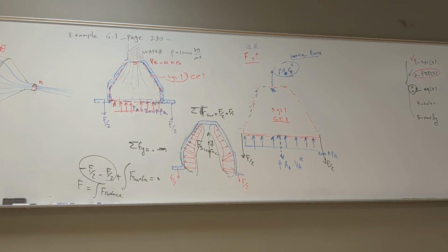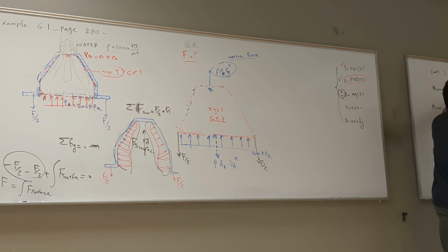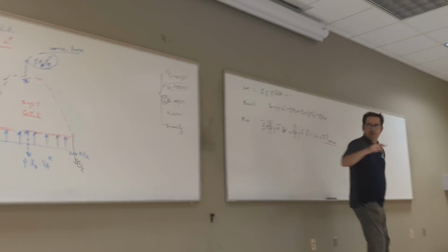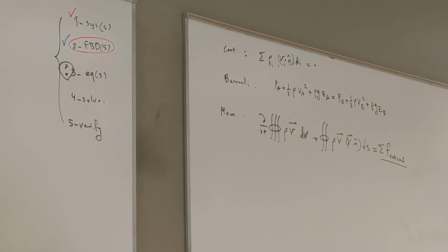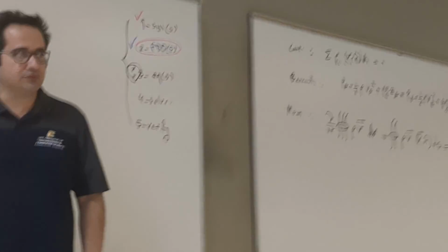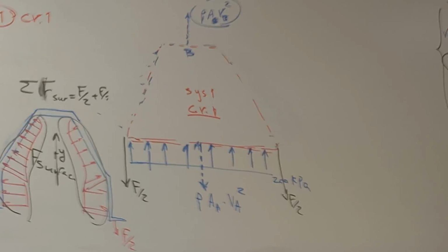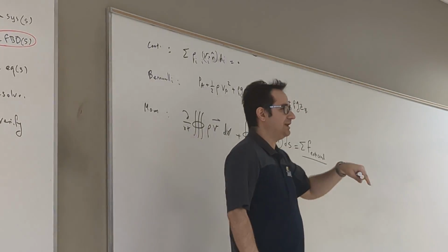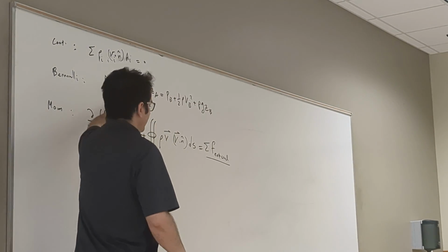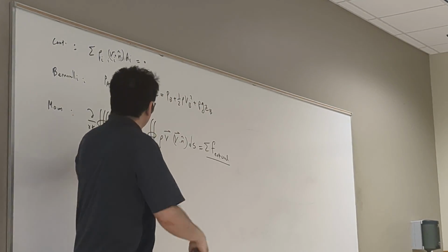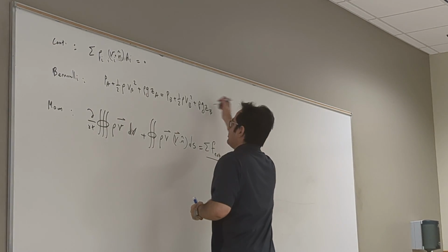Yeah, I can. In fact, you can immediately say that this equation in general is not valid. Why? Because of friction, you see? Where is the friction? This distributed load. So it's going to add effective friction, and these are all correlated. So there's going to be some pressure drop, like you saw in the lab 2 weeks ago. But for a moment, let's say it's frictionless. So I just take one stream in the core, and I approximate it. So this is valid, right? What about continuity?